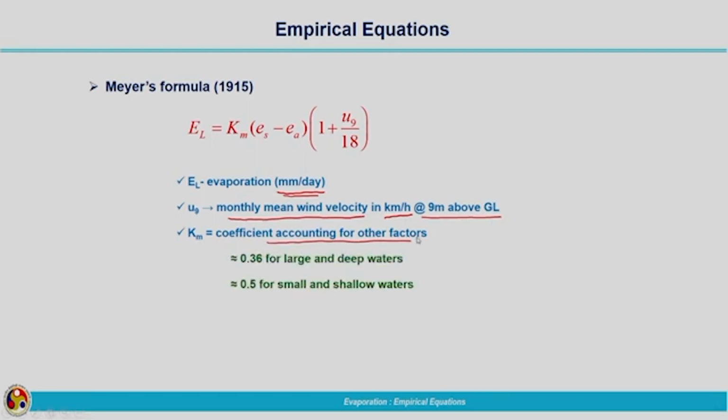When we were prioritizing the factors responsible for evaporation, we saw wind velocity, net radiation, vapor pressure, specific humidity, and also the area and the depth of the water body.